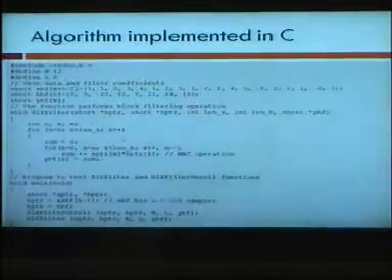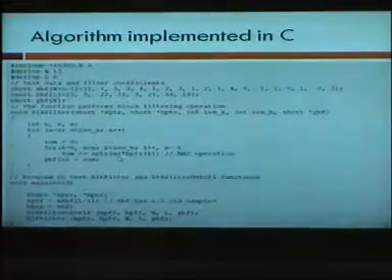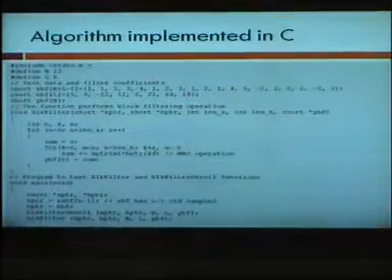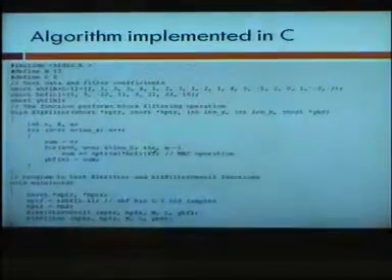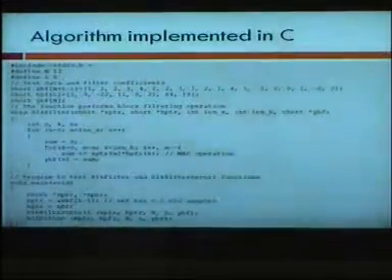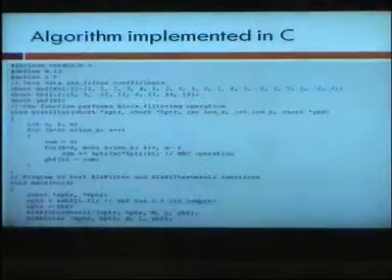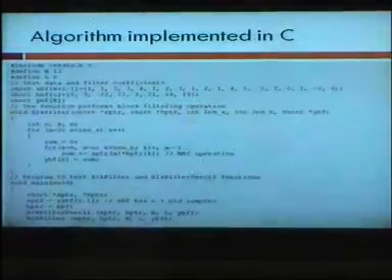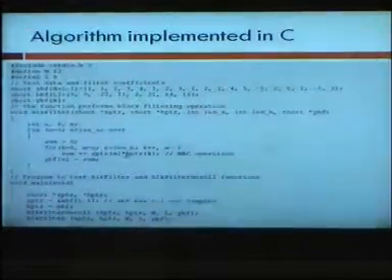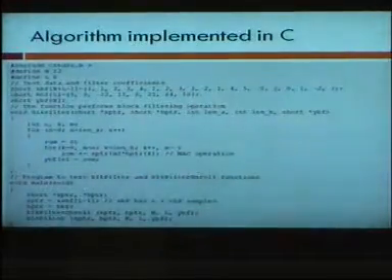What the for loop is doing is initializing. Then every time you run this one statement, which is actually multiplying and adding into the sum, you need to come back and check again. You need to add k, k plus plus, which takes a few cycles, then m minus minus, again a few cycles. Then you need to compare whether k is less than length of h or not. If not, you go down and implement. If yes, you need to branch. So just to execute one instruction, you spend 30-40 good cycles just to maintain the loop.